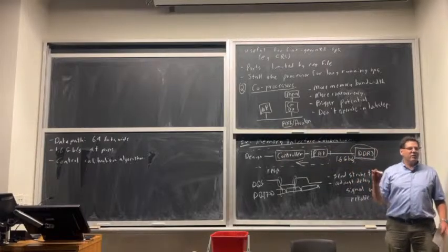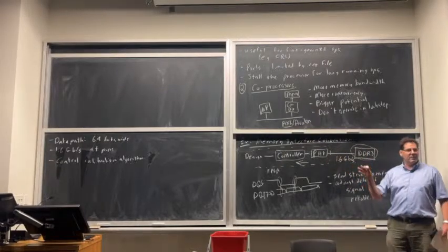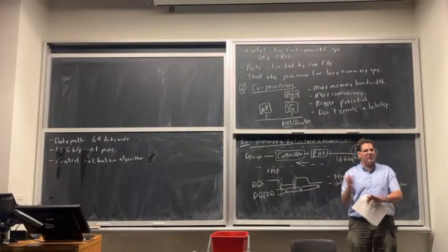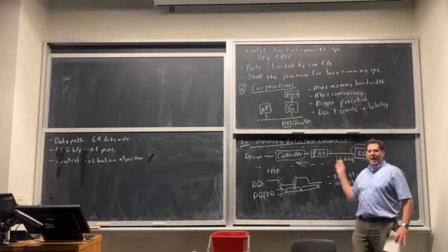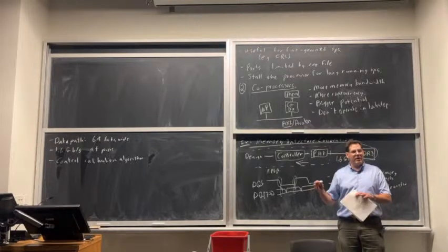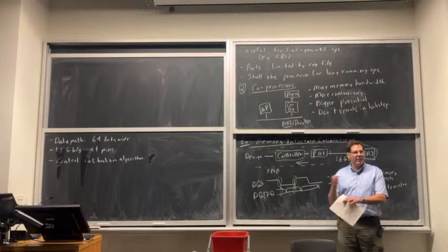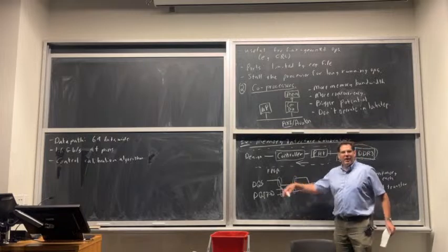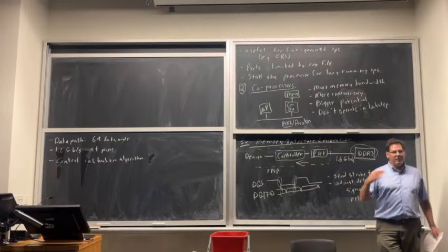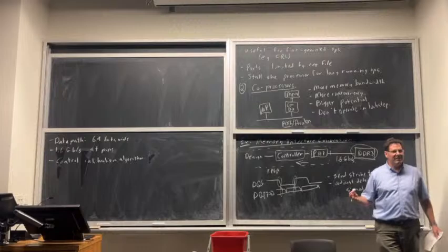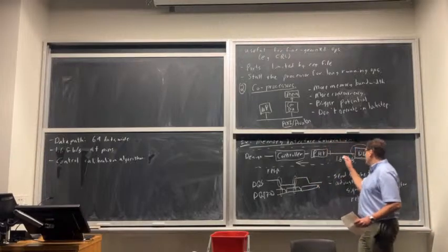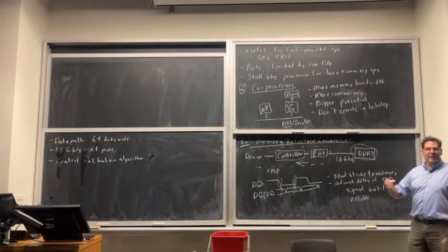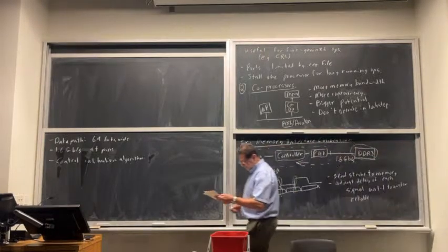And it starts sending test reads and writes with all sorts of different timings. It's basically just shifting around these DQS and DQs, and it's seeing what comes back. And it's got a whole algorithm in there to try to figure out, well, what should I do next, right? How do I shift these till I get reliable communication? And these algorithms are highly proprietary. So every vendor of FPGAs and other chips, they don't tell people how this works, okay? They keep it pretty secret. And as new standards come out, like DDR4 and DDR5, the algorithms keep getting more and more complicated, okay?